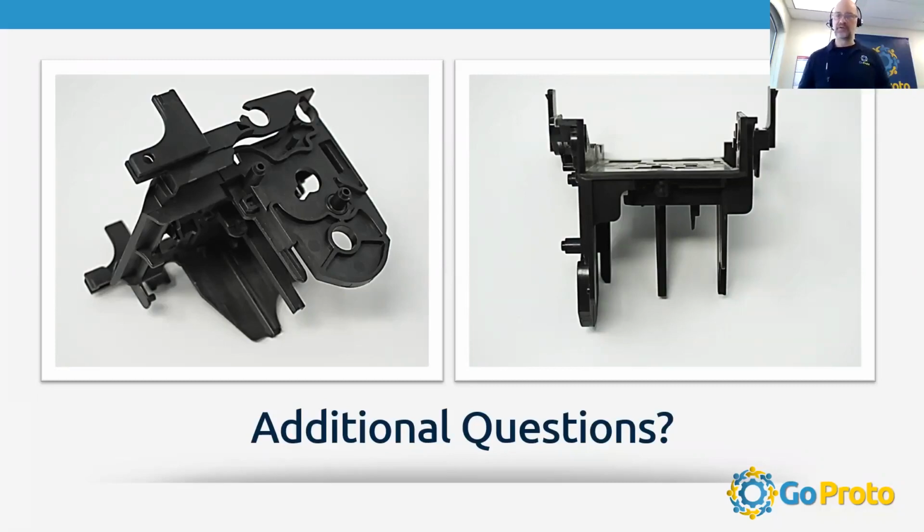There's a little bit different cost structure. It's a little different types of inspection, maybe components that are on the mold if it's designed to run on our machines versus someone else. Certainly a little bit more communication with design, mold design up front. If you're going to be planning to run it at another shop, we need to make sure that the connectors are the same, and that the sprue, which is where the gate runs in, is all the same. So we need to communicate that a little bit more. So might be a little bit more time. It is a little bit additional cost to have an export mold for that reason too.